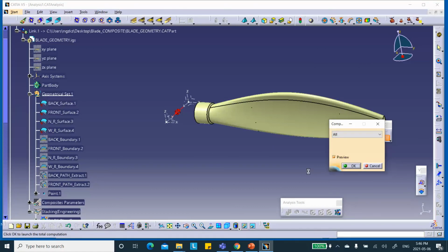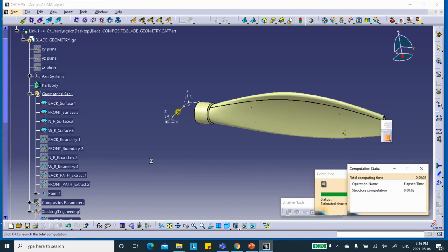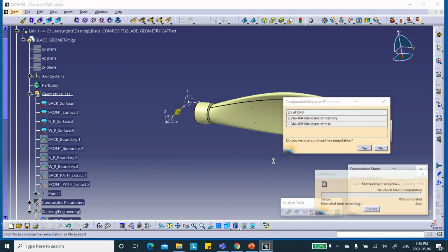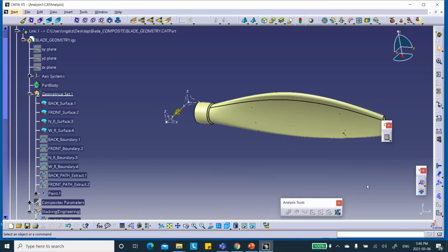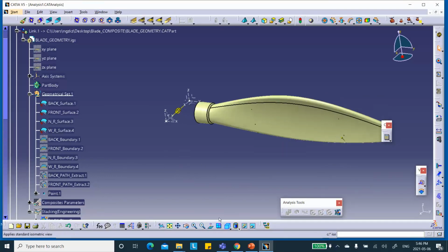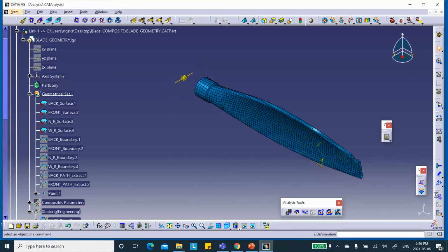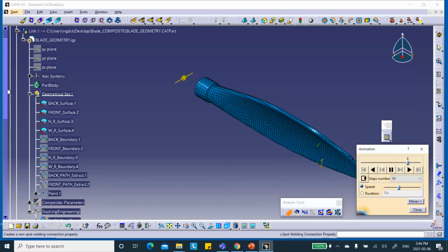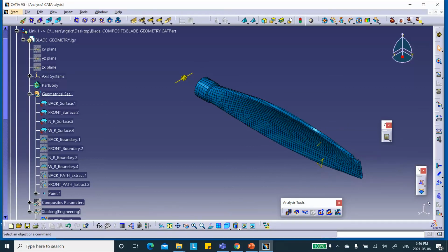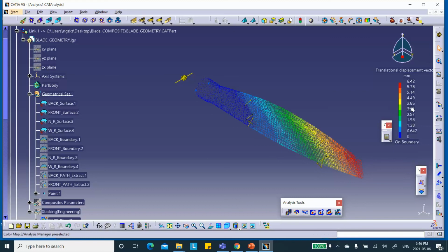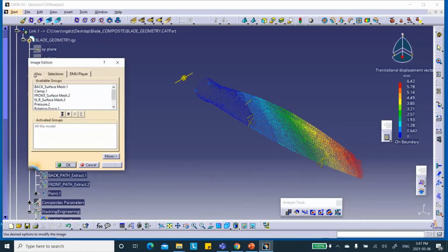All this mesh is not very good. I can assure you that one should not expect pretty answers here. But, okay, so it did run. Let's actually look at the deformation. There we are. In fact, you can animate it. You see that? So this is rotating, and this pressure is being applied to it due to aerodynamic forces, and this is what it looks like. Okay, very good. Let's look at the magnitude of deflection, about 6 millimeter. Okay, roughly 6 millimeter.